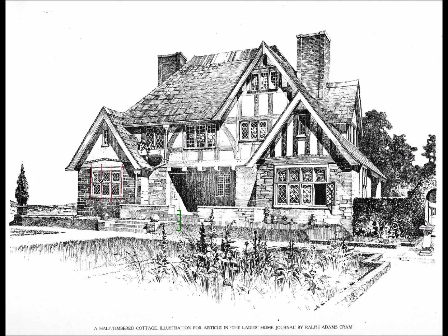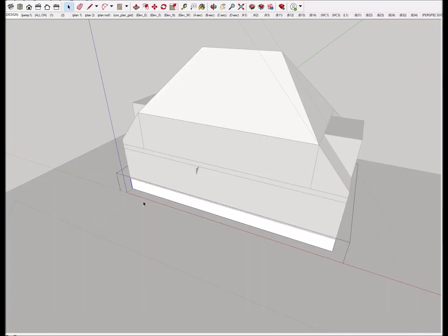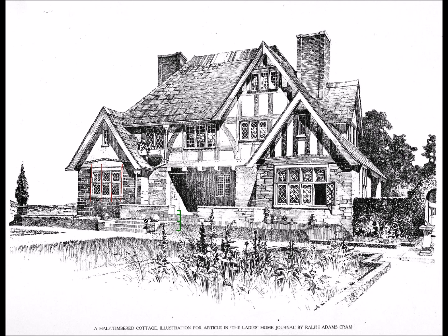We've got a porch to create, and we've got these gables to create, and a gable up on top, and we've got to finish this dormer and chimneys. I'll go ahead and do these 2 gables on either side. We decided they were 12 feet wide and 14 feet wide. As far as how much they project, it looks to me like it's about 2 feet.